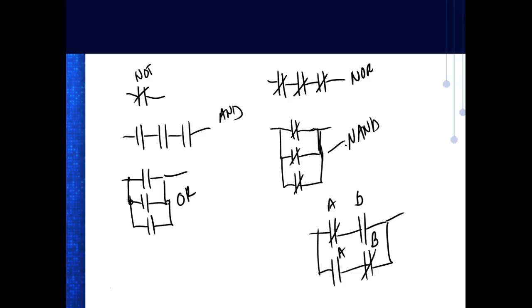Down here, if I use the term any, that's an OR. So any input will cause the output to be true. When I get over here, we're trying to figure out what's required to make it false. So if any of those open, the output's false. All these have to be open for the output to be false, right? You understand that?